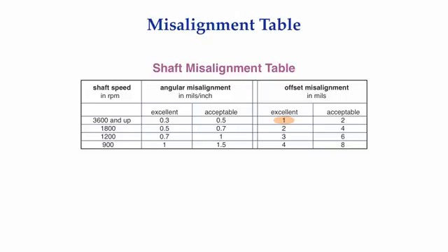Likewise, if you are trying to align a cooling tower fan drive system running at 1800 RPM, where there is a 15 or 20 foot separation between the coupling flex points, and you are trying to get the offset less than 4 mils, that is another waste of, well, hopefully you get the picture.